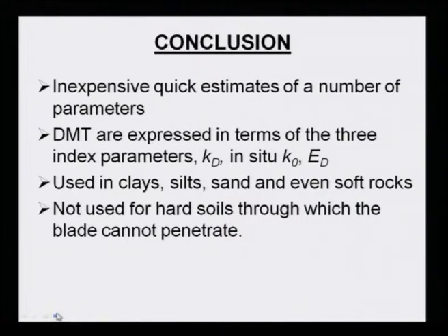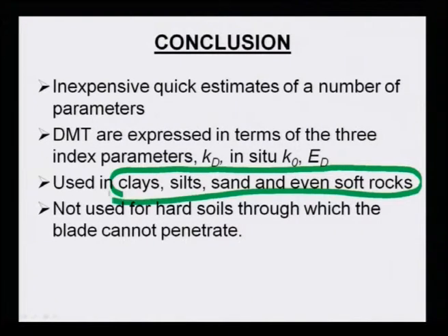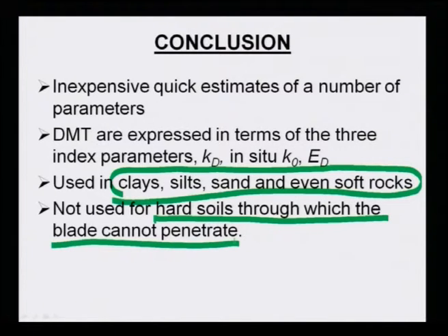DMT, the dilatometer test, is generally expressed in terms of three parameters, that is KD, in situ K0 and ED, used in clay, silt, sand, even also soft rock. However, it cannot be used for hard soil through which the blade cannot penetrate, because you have to penetrate that blade. For hard soil it is very difficult to penetrate that blade.